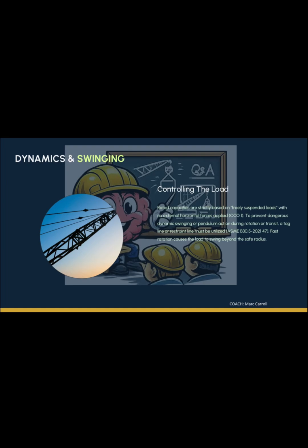When we talk about total load, we're not just talking about the crane picking up an actual load off the ground. The crane is loaded by the total load, not just the object. Rated lifting capacities include the weight of the hook block, slings, buckets, magnets, auxiliary lifting devices, the jib, if it's installed and you're not lifting off of it, and excessive parts of wire rope.